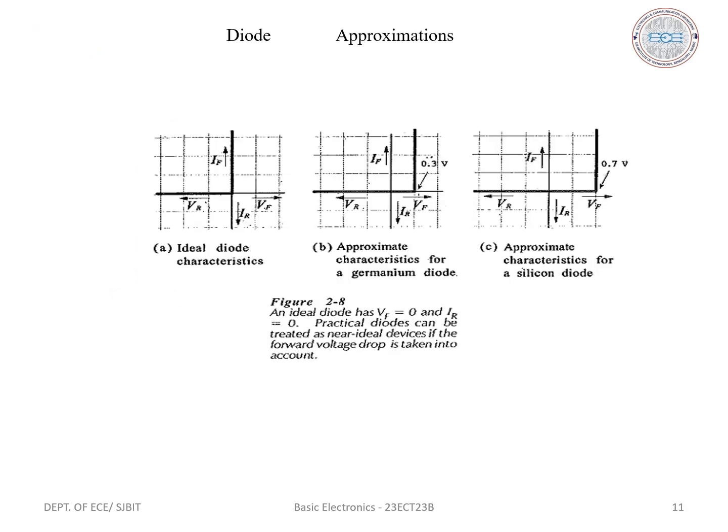Next, this is the diode approximation. Diode approximation is nothing but a diode equivalent circuit. An equivalent circuit for a device is a circuit that represents the device behavior under forward and reverse bias conditions. First one, ideal diode equivalent circuit. The diode conducts when it is forward biased and has zero resistance. The diode blocks the conduction when it is reverse biased and has infinite resistance, and it acts as an open switch.